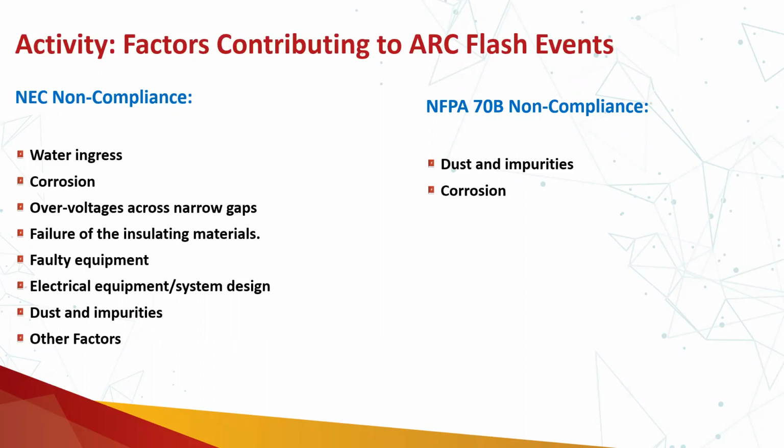That's why the dust and impurities accumulated, and it caused an incident. Corrosion. Okay, the electrical equipment was selected and designed for, and it was mentioned that this will be the rate of the corrosion. You have to maintain those electrical equipments or the installation by proper maintenance, by applying non-corrosive materials in order to either stop or lower the corrosion process. Water ingress, maybe after maintenance, the maintenance people did not put their backplates or the front covers in the right manner. That resulted in the water ingress.